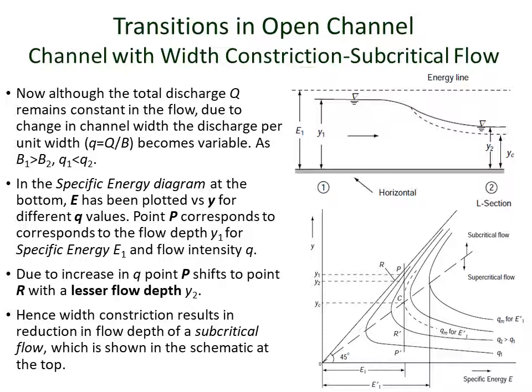So in the specific energy diagram, as we increase the discharge intensity, the curves shift rightward, and for a given specific energy, the flow depth actually changes to a lesser one.